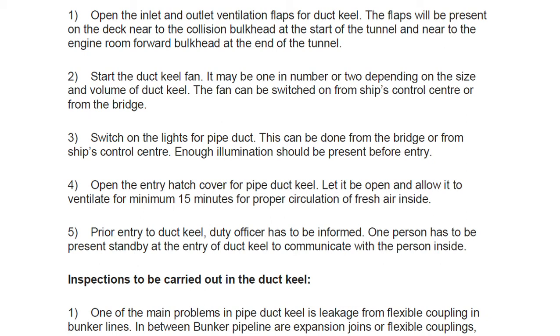So now these fans are remotely operated or locally operated. Both the mediums are possible. Switch on lights for pipe duct. So we switch on the lights for the pipe duct. This can be done from the bridge or from ship's control center. Enough illumination should be present before entry.